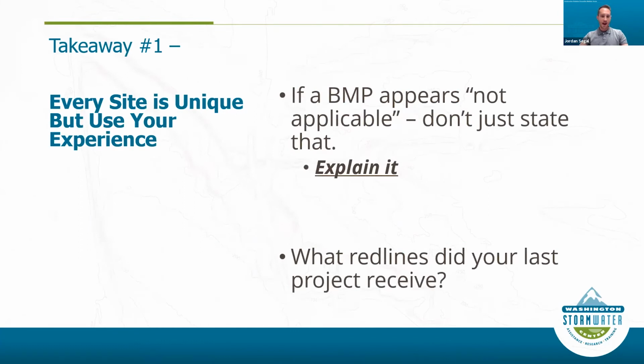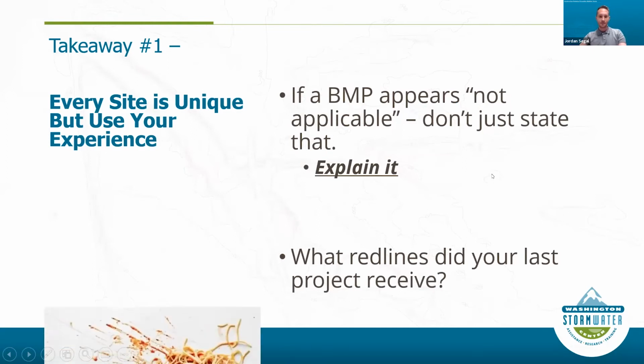So a quick takeaway, every site is unique. Go ahead and use your experience. Sometimes when you're filling out SWPPPs, people will write it's not applicable. I read that. And when I see not applicable and that's it, that's not cutting it for me. I need to see an explanation. If there have been red lines about a BMP on a previous submittal, don't just ignore them. Call your reviewer. We're more personable than we think. We'd love to talk to you about these things.